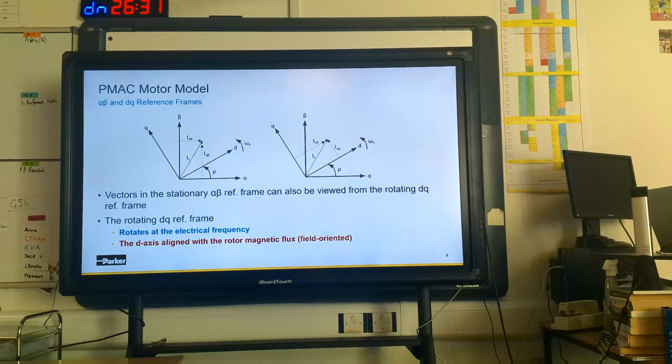Can I just ask, how do you work out where the rotor alignment is at any one time? Is there a separate sensor or tacho or separate motor? No, you measure it. You have an absolute position encoder. You put it on the shaft. I see. You measure the position of the shaft. So it is an extra feature of the motor? Yes. We could talk about sensorless vector control, but that would be a whole other lecture. I had to cull this down to 30 slides. I'm sorry about that. Maybe that's a talk for another time.